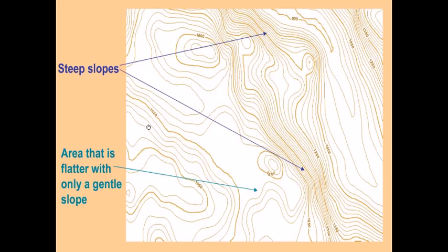And another thing to see is that some contour lines are bolder. So we talked about this. These are called index contours, the contours on which you mark down the elevations. And then the contour lines between two index contours have elevations midway. And depending on what is the difference between the two index contours and how many lines you have, you can find out the contour interval, which is the difference in elevation between two successive contour lines.